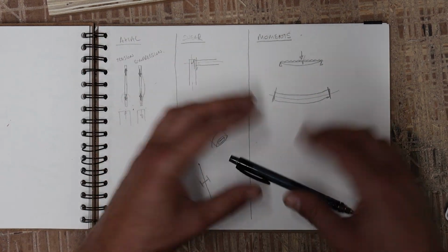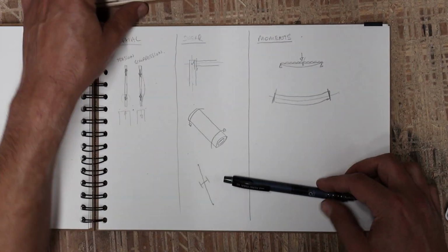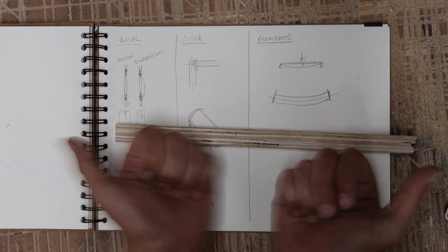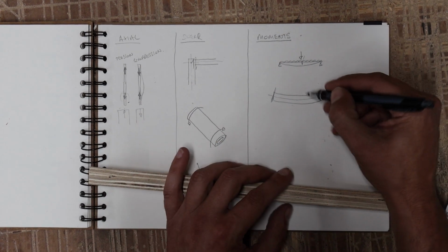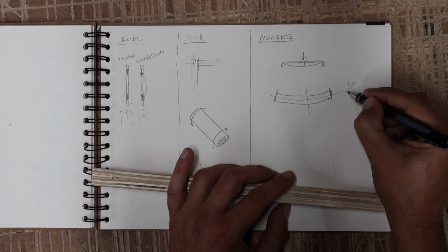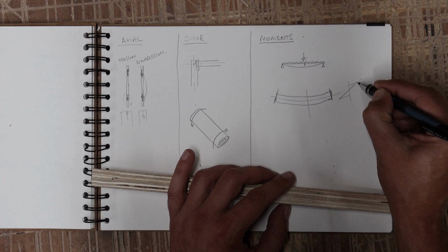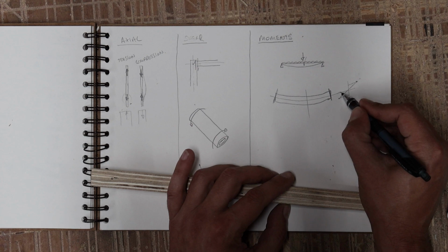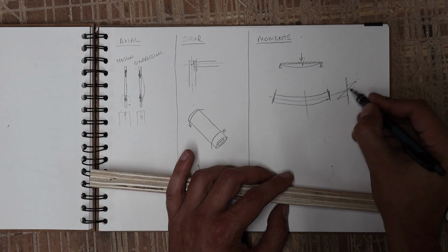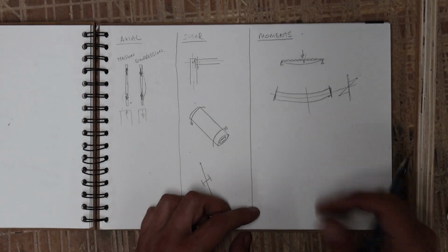That's the technical language, that's the technical way of seeing it. You get a compression in the top part of the member, and you get a tension in the bottom part. And if we took a section through, that force would start off in one direction, it would come down across. So we would get two peaks, one at the bottom face, one at the top face, and then along the center line, the shear force would be 0. You know, if this line represents the 0 shear force, and this, yeah, I hope that makes sense. Again, I'm going into quite some detail. You know, I don't know whether this is relevant.